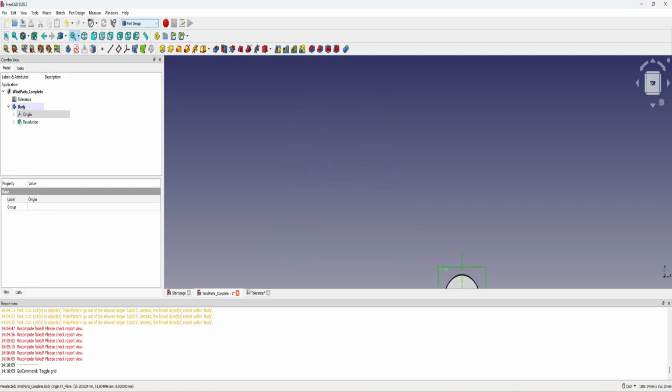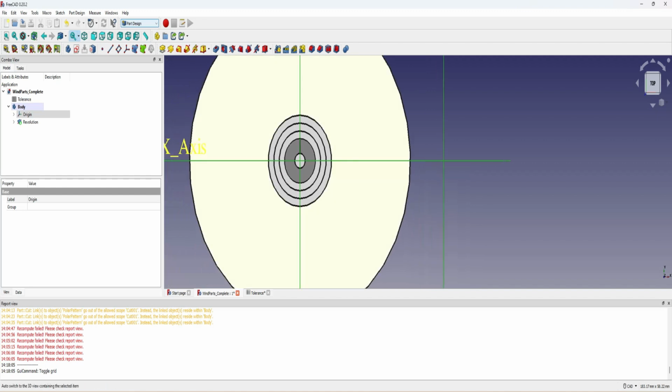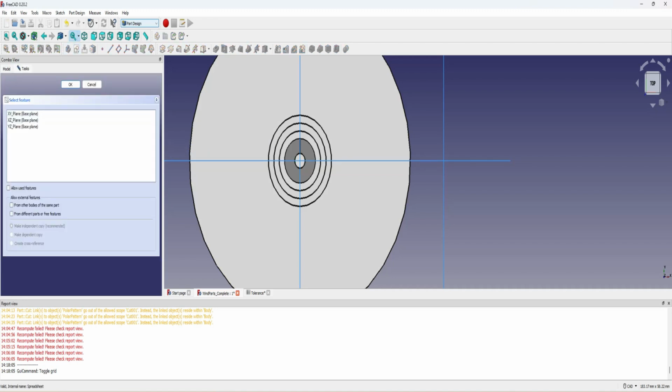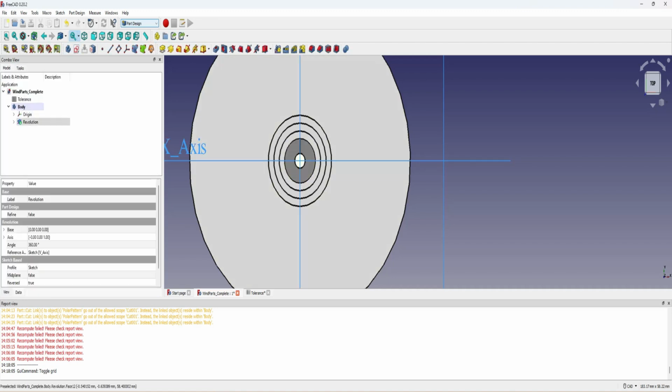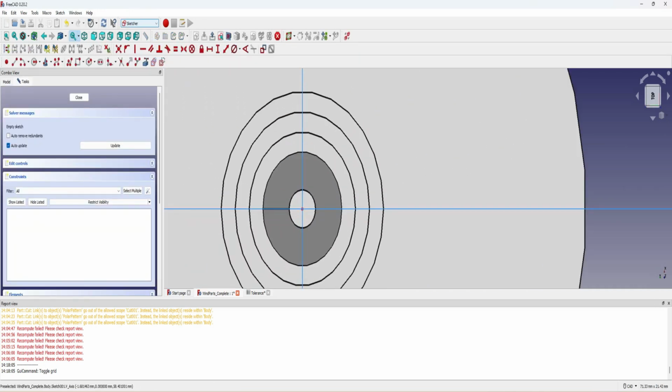There's a few other things I need to do to this revolved part. I need to cut some notches in the very top so that it can fit into the design that I'm trying to fit it into. So once I've selected the very top of the part, create a sketch on the very top part. I'm going to draw 2 boxes, and the 2 boxes are going to make up like a jig to cut out the portion of the circle or the cylinder that I don't want anymore in order to make it keyed to fit onto the device that it's being fit onto.